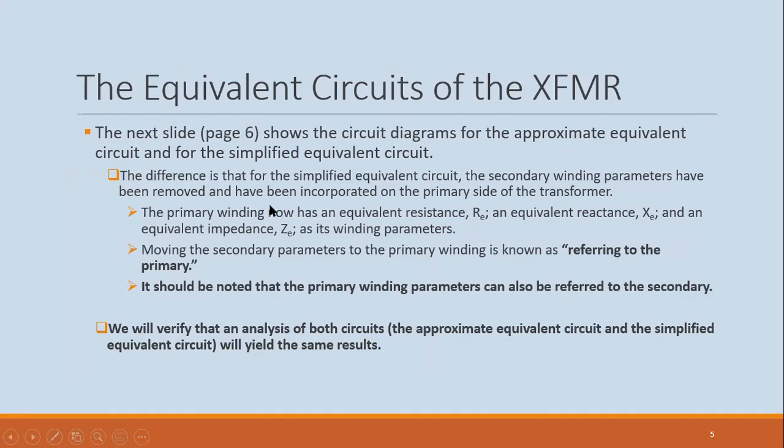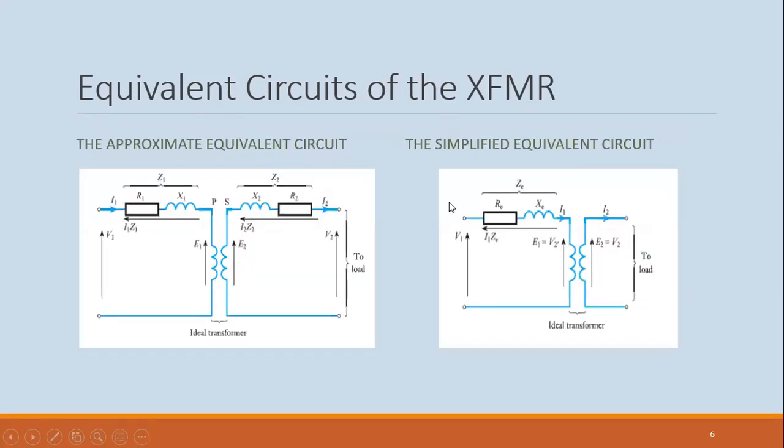So in the next slide or so, I will show you the difference between the approximate equivalent circuit and the simplified equivalent circuit. And let us just look at it. So the approximate, notice no core parameters here. And then the simplified equivalent.